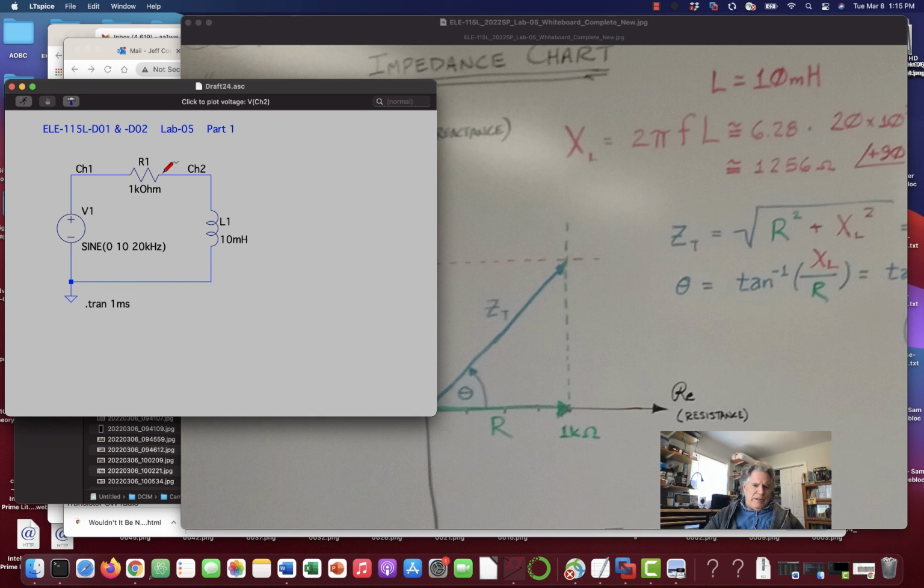Resistors are, as we've always said, things that turn electrical energy into heat energy immediately. And so there's no phase shift or delay going through resistors. Remember also that sine waves are great for this kind of analysis, because sinusoids are the one waveform that when you put them into circuits containing resistors, inductors, and capacitors, which we'll learn about, the waveform that goes through the circuit at any point is always a sine wave or sinusoid. It's a really neat property.